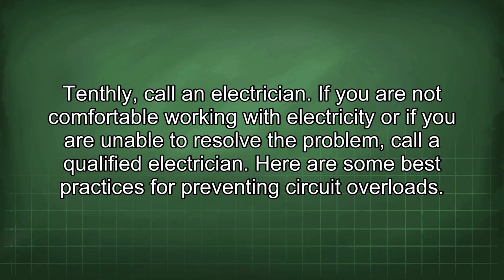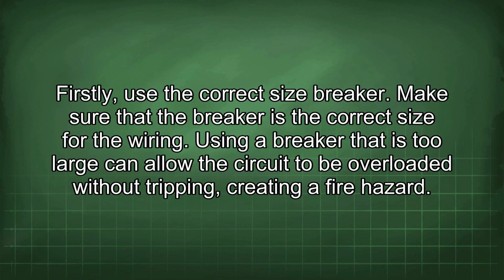Here are some best practices for preventing circuit overloads. Firstly, use the correct size breaker. Make sure that the breaker is the correct size for the wiring. Using a breaker that is too large can allow the circuit to be overloaded without tripping, creating a fire hazard.